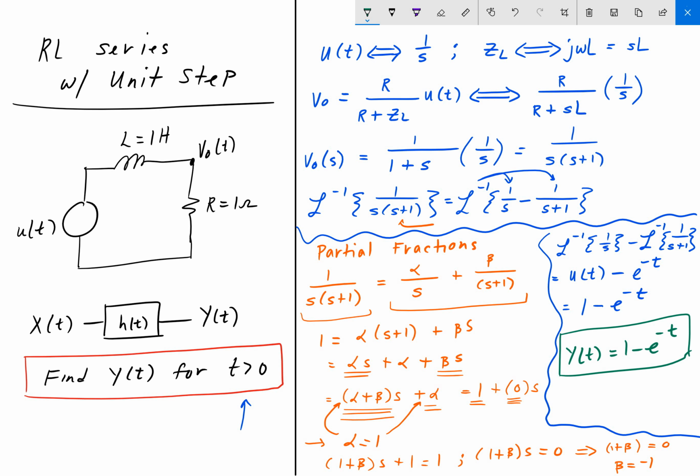You would have had to do an integral of an exponential, which I guess is not too bad, but for easy functions like these, for which we already know the transforms, it's sometimes easier to convert to functions of s rather than to convolve them. And so that's what we did here. We used knowledge that we are very comfortable with, like voltage divider, and took the inverse Laplace of this voltage divider that we're pretty comfortable working with.